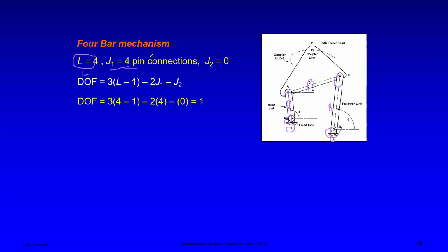Now, having gotten all our pins, which are 4, how about another motion, a constraint for 2 degrees of freedom? It is not there. So we are going to substitute in our formula, whereby we put in our 4, 4, and then we realize this one is also a 1 degree of freedom. It's also a mechanism, right?